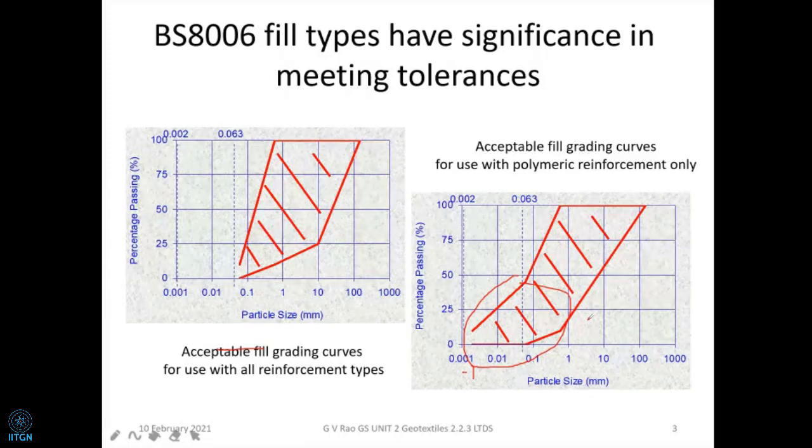Also, we know that the fascia is there. We will go into details much later. In India, we use a 180 millimeter thick fascia of precast concrete panels. Instead of a regular RC wall, we use a very thin fascia. So the thin fascia needs no foundation, and the width of the foundation soil is large, so there is more bearing capacity.